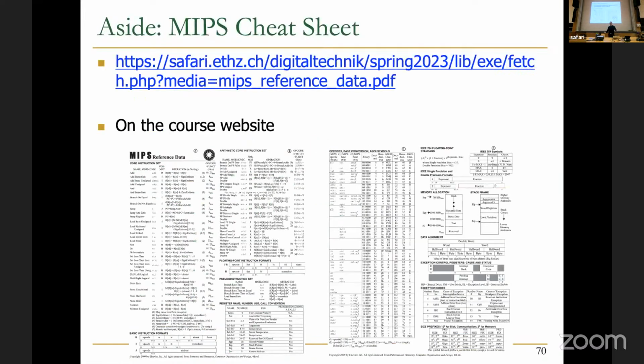Okay, so basically, if you want to design a MIPS processor, you should take the MIPS ISA manual, which is not this one, this is a cheat sheet. The MIPS ISA manual is long. You basically need to provide the support to execute every single instruction: the data path support, the control signals, and then the control logic support. Basically, you need to repeat what we have done for hundreds of instructions and make sure you didn't do anything wrong. Makes sense, right? So this is basically, we start from a blank slate.